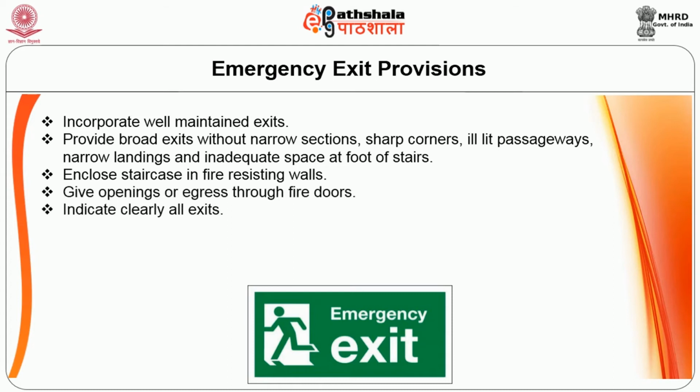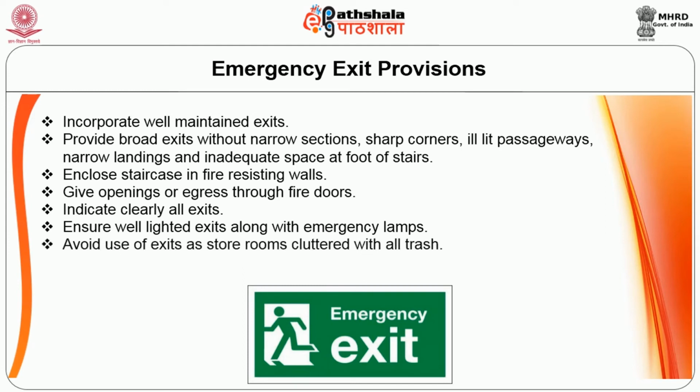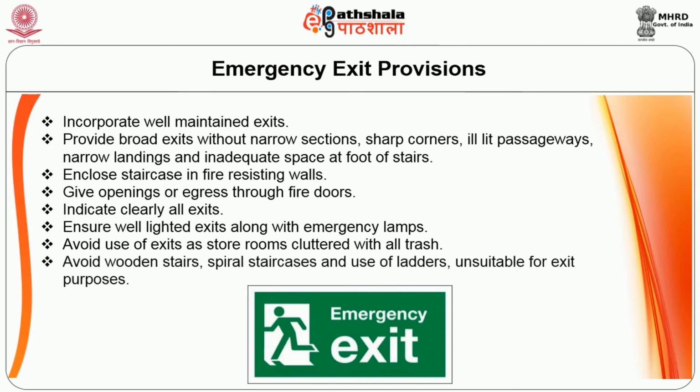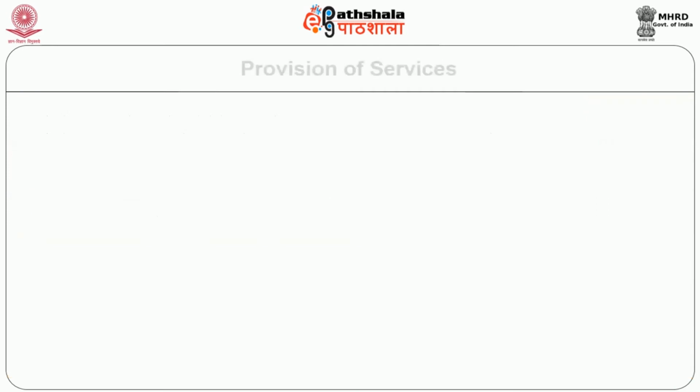Indicate clearly all exits. Ensure well-lighted exits along with emergency lamps. Avoid use of exits as storerooms cluttered with trash. Avoid wooden stairs, spiral staircases, and use of ladders which are unsuitable for exit purposes. These ideas, again if given due relevance, can definitely help prevent fire accidents.